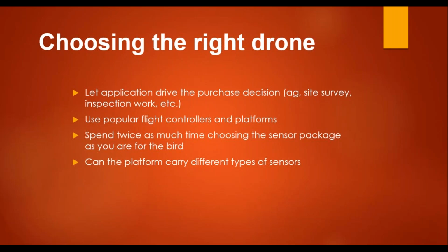So they can use the lidar technology, of course. Lidar is a laser detection and ranging sensor, from which we can identify the distance of an object from one place to another. If the sensor is deployed on the UAV, we can easily identify the distance of a particular object from the UAV itself. So lidar technology is also being used in the UAV. Not only UAVs: Apple has come with the new iPad Pro, in which they have embedded a lidar sensor with the camera itself. So we can see how technology is going forward, and everybody is going to use these technologies to project AR VR kind of stuff. That's why lidar is an important sensor.